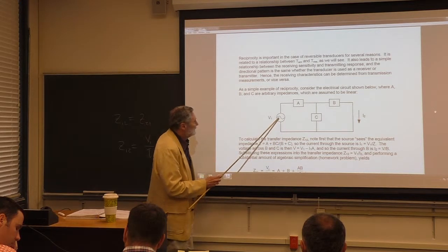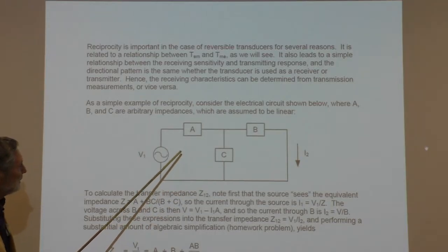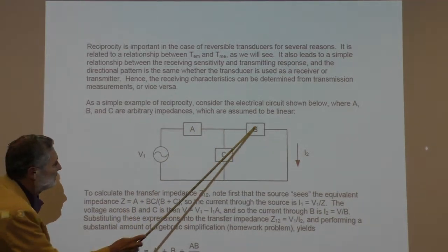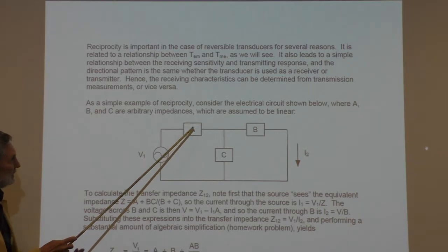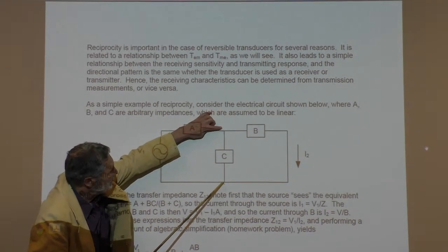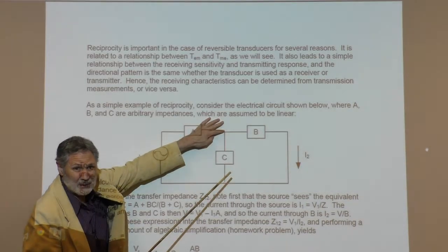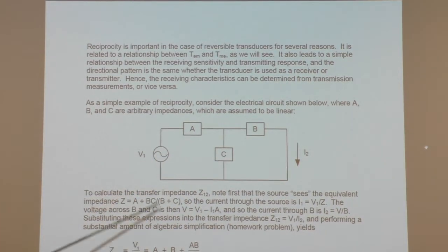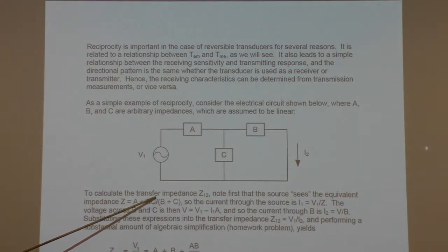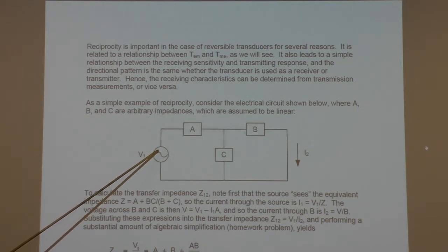But here's briefly the idea. This voltage source here sees an equivalent impedance here, right? And the equivalent impedance, I see this impedance in series with these two impedances. So this sees an impedance, which is the impedance A, plus the parallel combination of these. And the equivalent impedance across these two points right here, 1 over that is going to be 1 over B plus 1 over C, right? Impedances in parallel add in reciprocal. So we know what the impedance is, and here I've converted the reciprocal, 1 over the reciprocal, here. We'll go through all this. So this is the impedance seen by the source here.